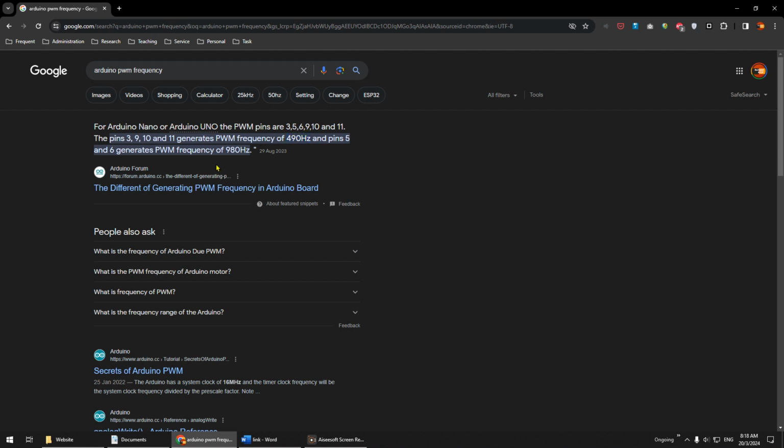So basically when you search Arduino PWM frequency, you cannot just search like that because the frequency is fixed. But in power electronics the frequency is usually in kilohertz, around 20 kilohertz to 100 kilohertz normally. But for the default PWM you will get this, so you basically cannot use the original code. To avoid this problem, which normally happens to students, you have to use a modified code that can run the frequency higher.